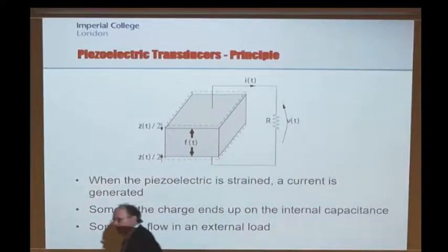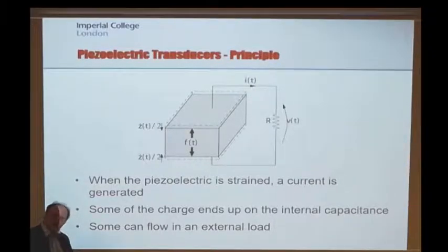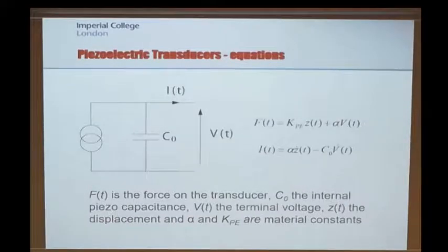The last one, and the one that you've now spent the most time looking at, of course, is the piezoelectric approach, where if we strain a material, then that deformation gives us charge separation within that material, and we get a voltage. So as we bend that piezoelectric cantilever, we put charge onto the capacitance of the model for the piezoelectric material. And once we've done that, we've built up a voltage. Then, of course, we can use that voltage to supply an external load.